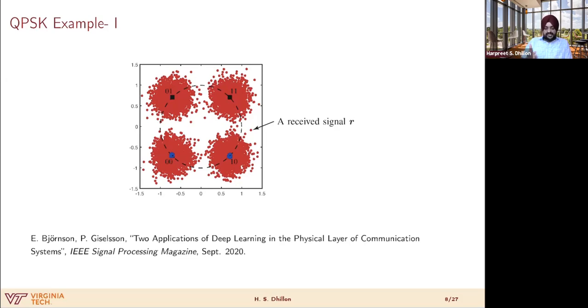Now you transmit a signal, right, and use an AWGN channel. Your received signal is obviously not going to correspond to this constellation point. It may be close because you have Gaussian noise, but it is not going to be exactly that same point that you transmitted. So what you eventually get is a sort of cloud of points around each of these constellation points, right?